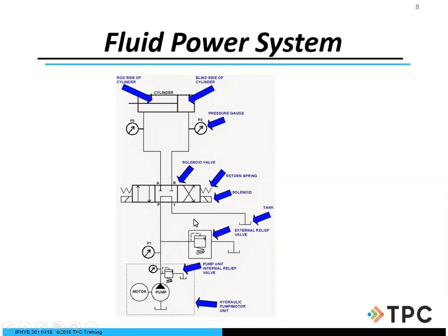So you might see 2 or 3 tank symbols over here. I've got 1 tank. That's all it really means. But everything is flowing back to the tank. That's what it's telling us. And then we have our directional control valve over here. So this guy is more than 2, right? We've got 1 envelope, 2 envelopes, 3 envelopes. So that's 3 position, 4-way on this guy. And then we have our solenoid. So it's electrical. In most cases, we have a range from 12 volts DC to 24 volts AC on our activation of these solenoid valves.